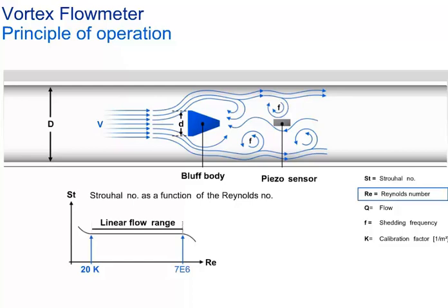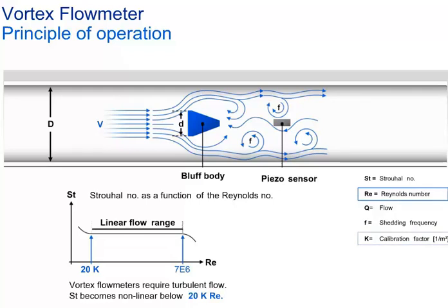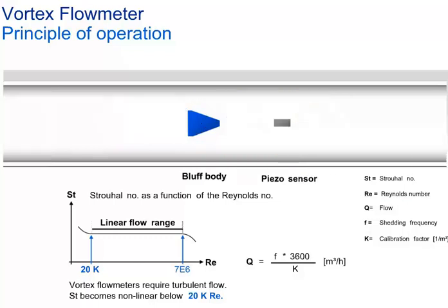vortex remains the same. To find out what volume is transported per vortex, each flow meter is calibrated to evaluate the meter K factor, which is frequency over flow. During operation, the flow meter calculates the actual volume flow from the measured frequency and the meter K factor. In other words, every pulse from the sensor represents a certain volume V, regardless of the substance of the volume. This is why the calibration procedure is widely independent of the subsequent application.